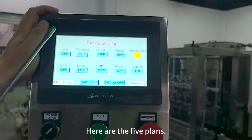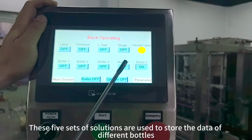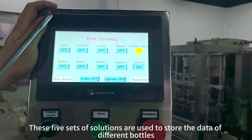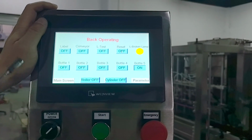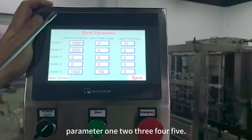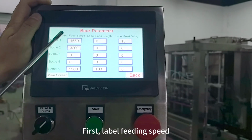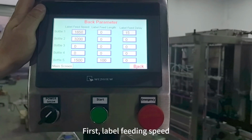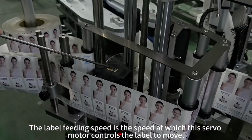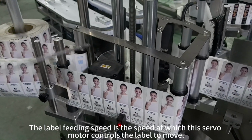Here are the 5 plans. These 5 sets of solutions are used to store the data of different bottles. We go into its parameters. Parameters 1 to 3 for 5. We often set 3 parameters. First, label feeding speed. The label feeding speed is the speed at which this servo motor controls the label to move.